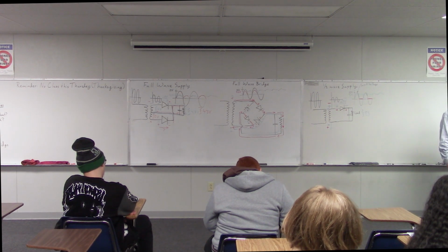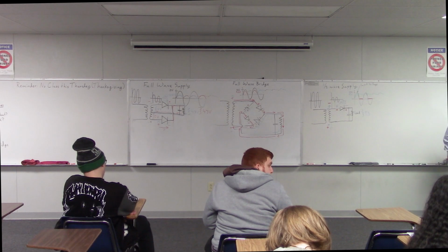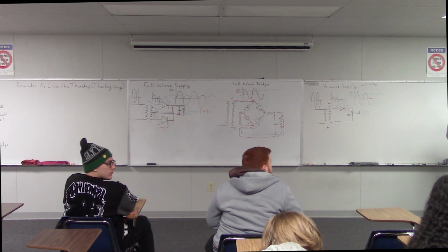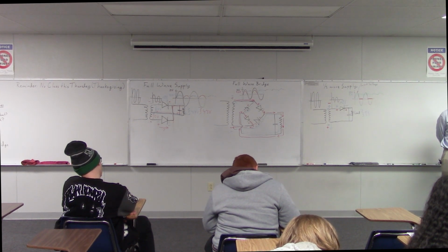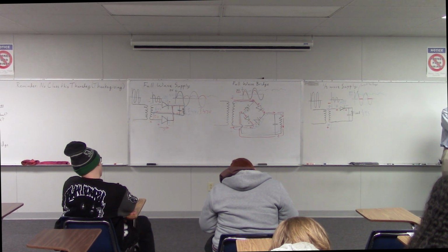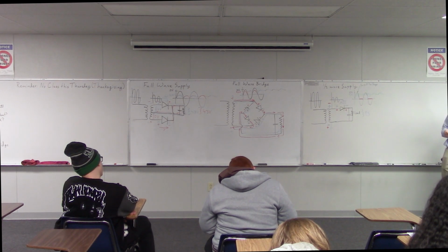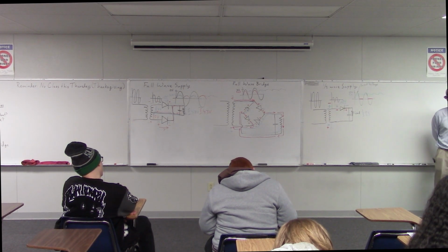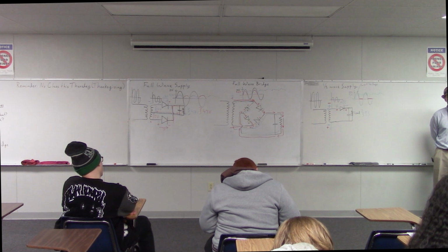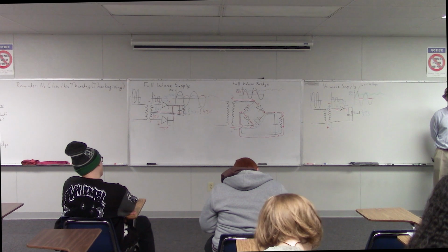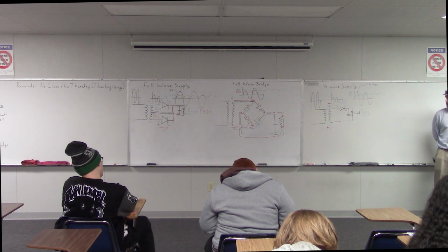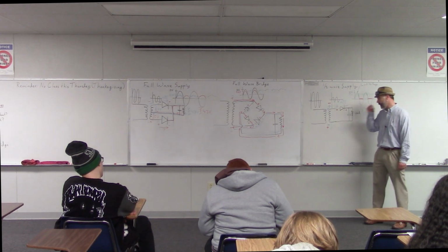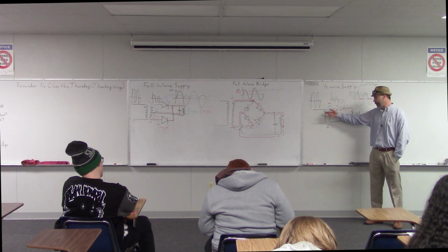When I disassemble electronics, I've seen what I think are supposed to be step-down transformers from the main line that are so small that I doubt they can actually take 120 volts in the first place. Oh, you can get very small transformers, and they can handle 120 volts. Is it common practice to try to attenuate the wall power before feeding it into a transformer, or do you just put 120 volts straight into it? Yeah, typically you just put 120 volts straight in,